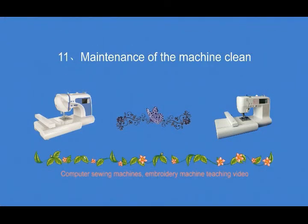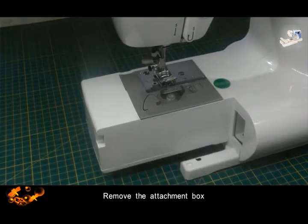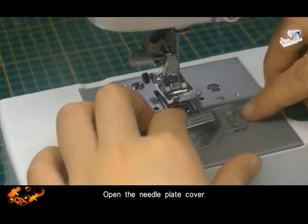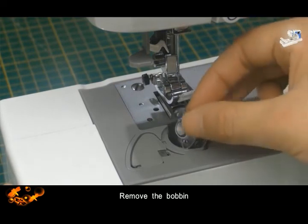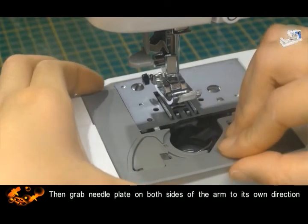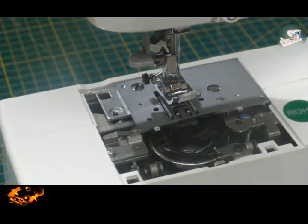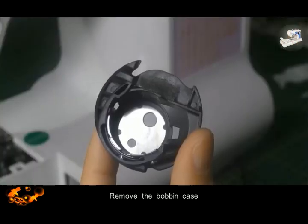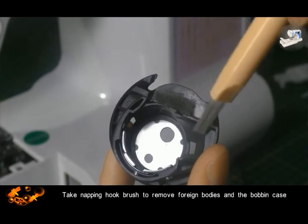11. Maintenance and cleaning of the machine. Shut off the power. Remove the accessory box. Open the needle plate cover. Remove the bobbin. Then grab the needle plate on both sides of the arm and pull toward yourself. Remove the needle plate arm. Remove the bobbin case. Take the napping hook brush to remove foreign bodies from the hook and the bobbin case.